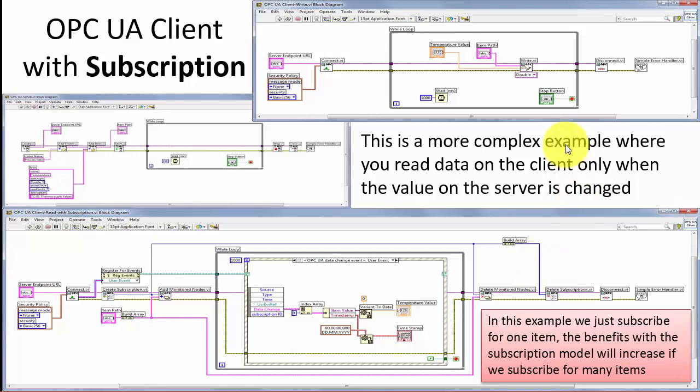In this example, we are not going to create it in LabVIEW. We will just show how it works. So here, in this case, we have an OPC server similar to the previous one, and then we have an OPC UA client that writes data to the server, and then we have the second client here that reads the data from the server.